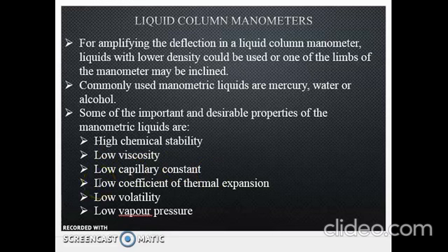Also, the manometric liquids with low coefficient of thermal expansion would be preferred so as to minimize the ambient temperature effect on the pressure measurement. Next, an important characteristic of the manometric liquid is that it should be low volatile, so that there is no vaporization of the manometric liquid if the application is in the high temperature region, and it should have low vapor pressure. So these are some important and desirable properties of the manometric liquids.